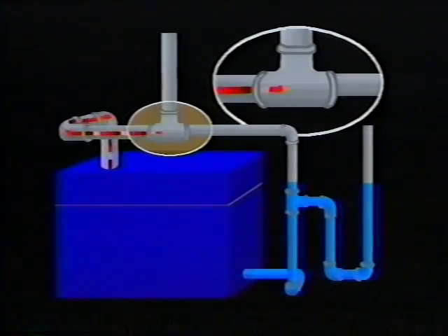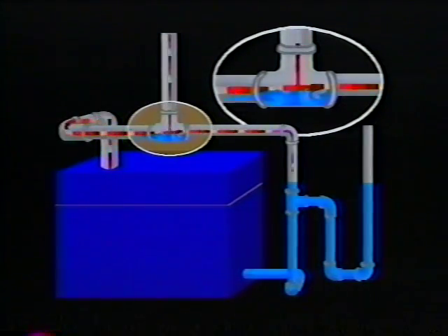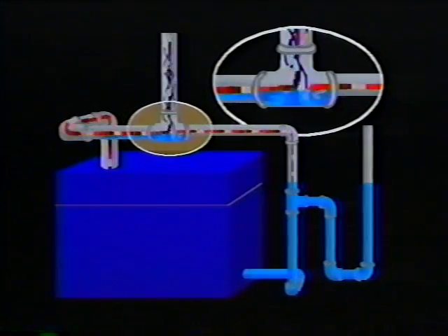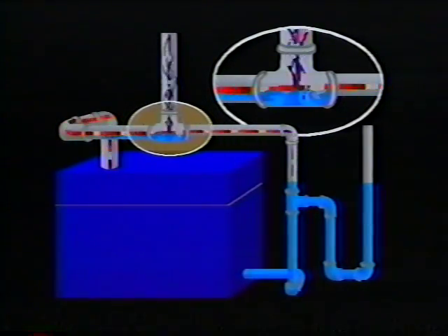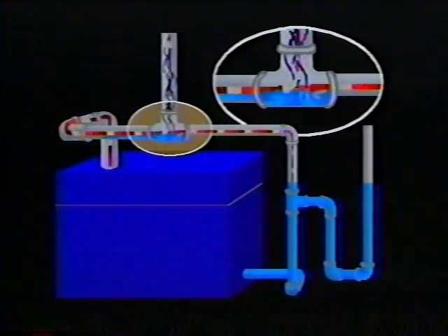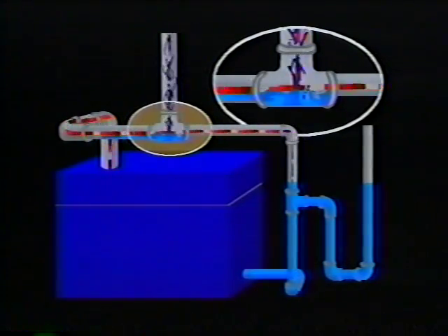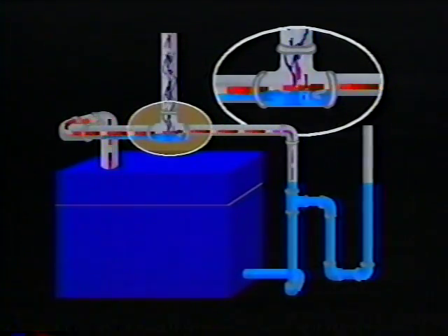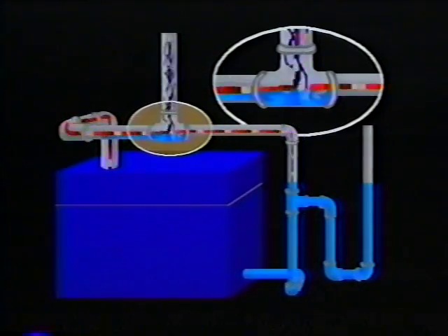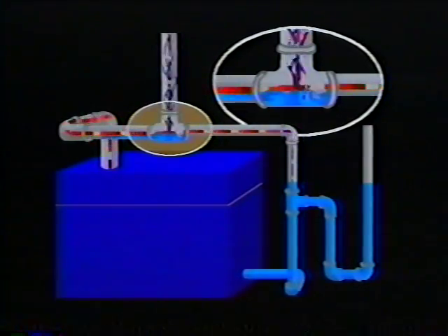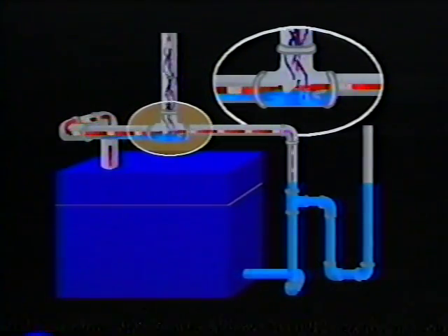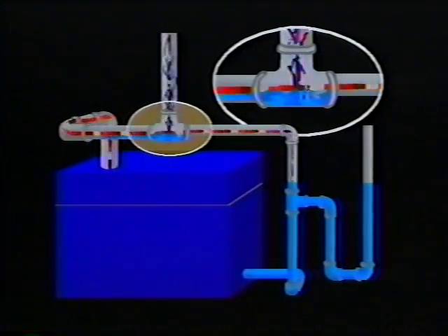Water trapped in the header reduces the effective diameter of the header, forcing steam flow through a smaller opening and at a greater speed. The speed or velocity of the steam can carry water out into the system, causing water hammer and an immediate reduction in water level. Again, consult manufacturer's instructions for proper header and equalizer sizing.